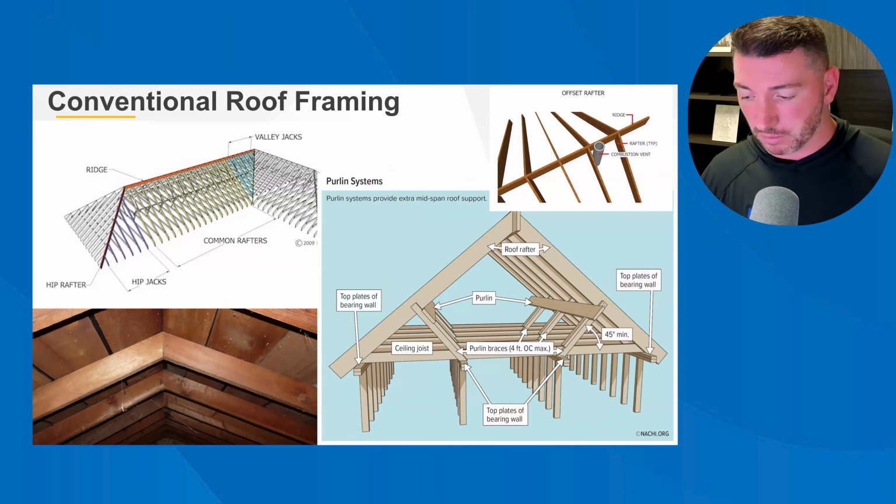Sometimes rafters do have to be moved a little bit to accommodate components of other home systems. That illustration above on the right, top right, shows an offset rafter to accommodate a vent pipe. If you see that a lot of the rafters don't align, you might make a comment on this, but in existing homes, refrain from calling it a defect unless you see an indication of a major failure.